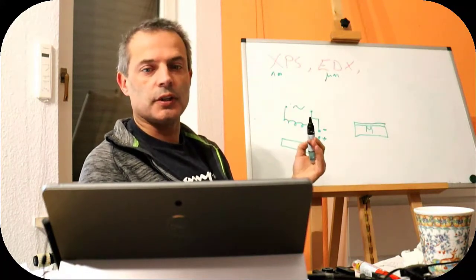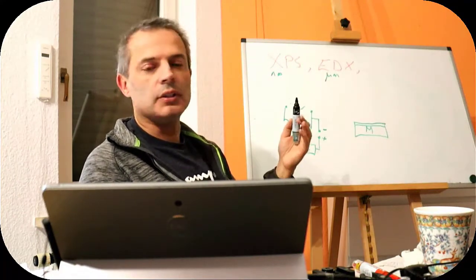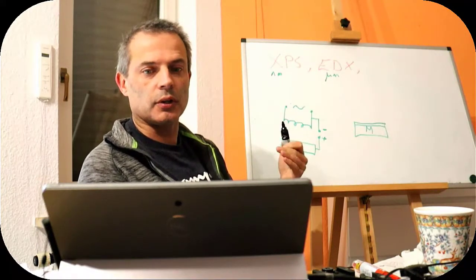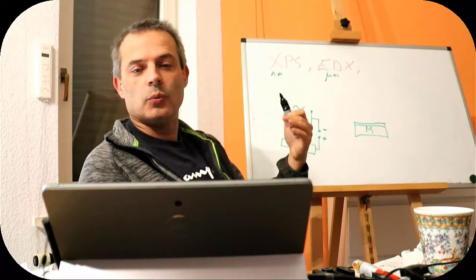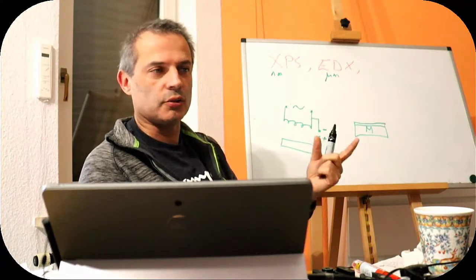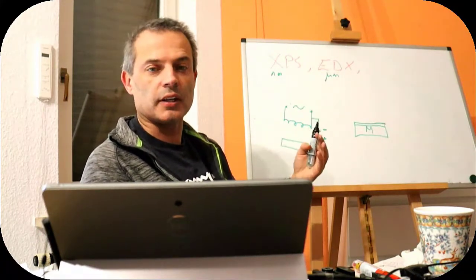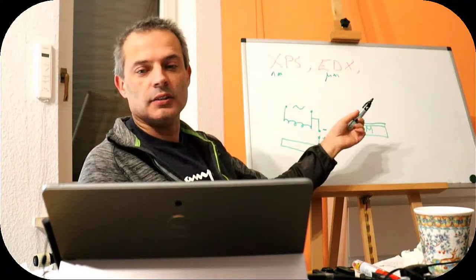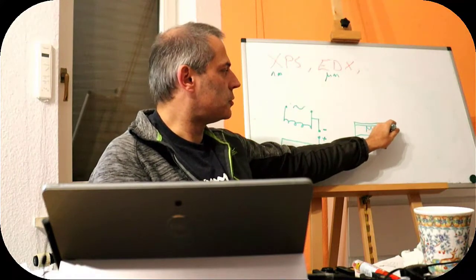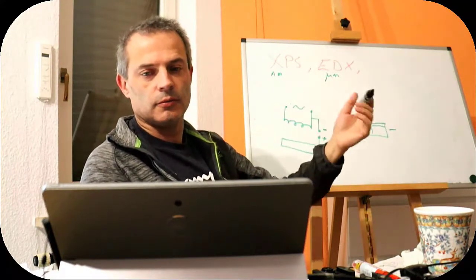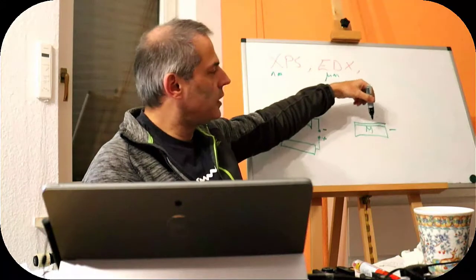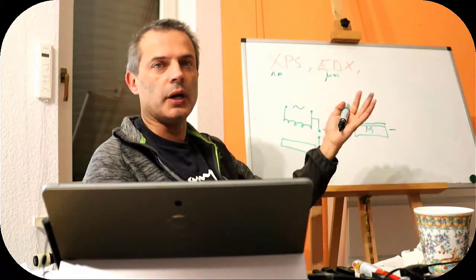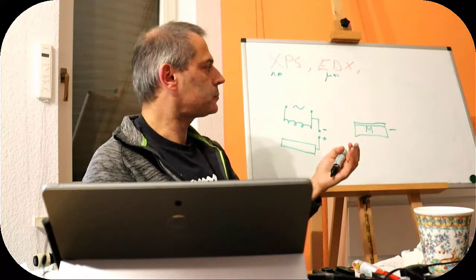So we need lots of energy in our electrons, and that means that either we're going to have a lot of stages of electrical power that we're going to have to put in, or we're going to have one high electrical power, and so we don't want to have that as well. The other problem with electrical power is because we're going to have to charge this to a very high negative voltage compared to everything else, it's going to then be attracted, and if it's a thin piece of wire, it will bend and distort and get damaged.